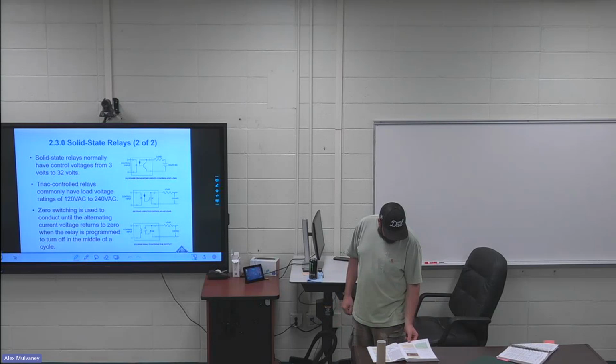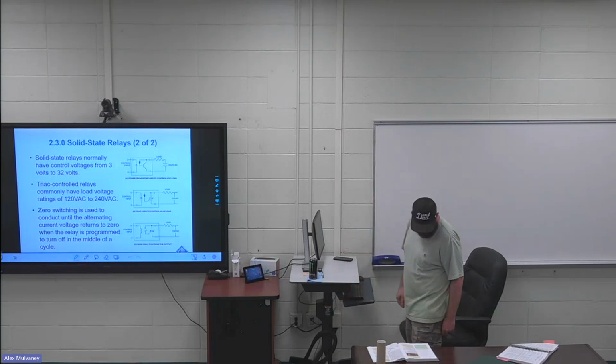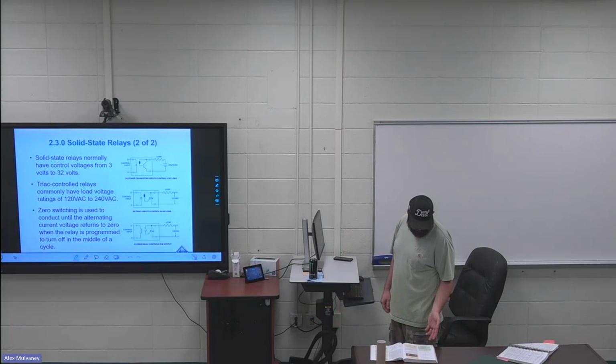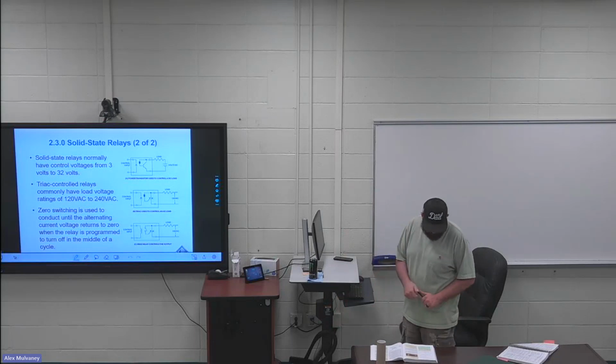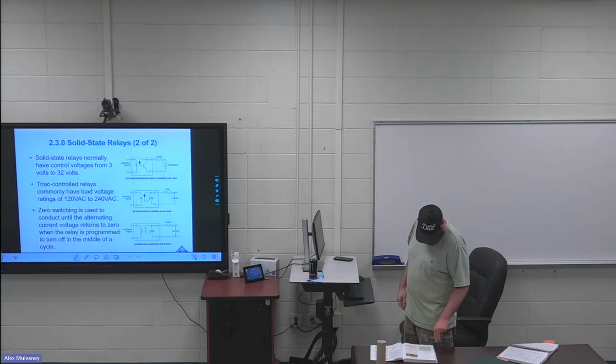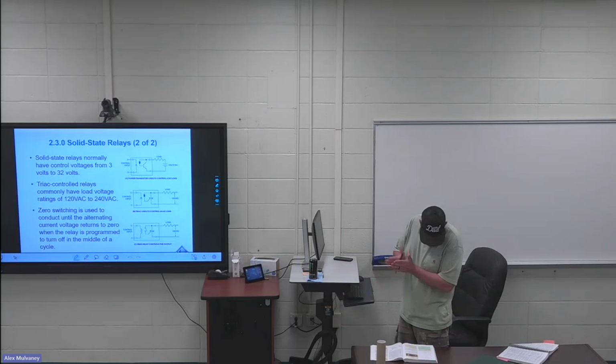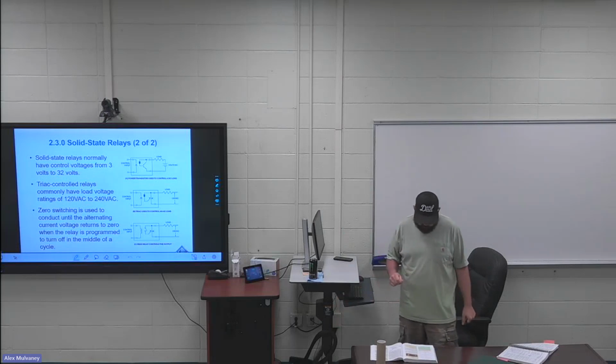Moving on from there, different types still have more. That's the first, that's the A one. And then moving on to page 14, I don't have anything in the triac controlled AC relays, but those are used quite a bit. The third bullet point, the whole thing is highlighted. Another method of controlling solid state relays in the AC circuit is to use a small reed relay to control the output, as shown in figure 13C.